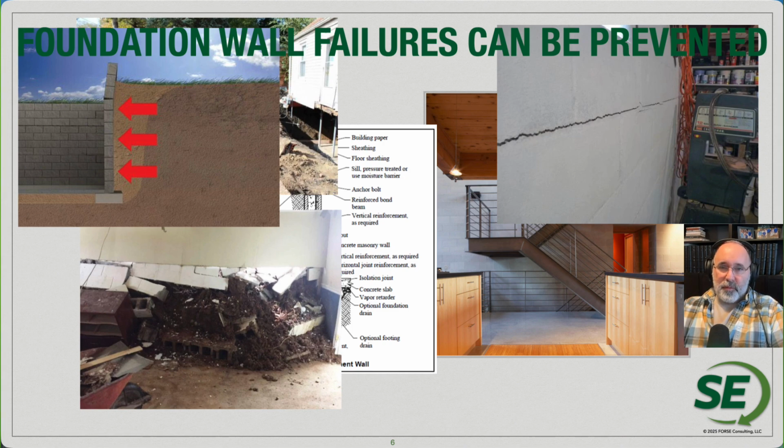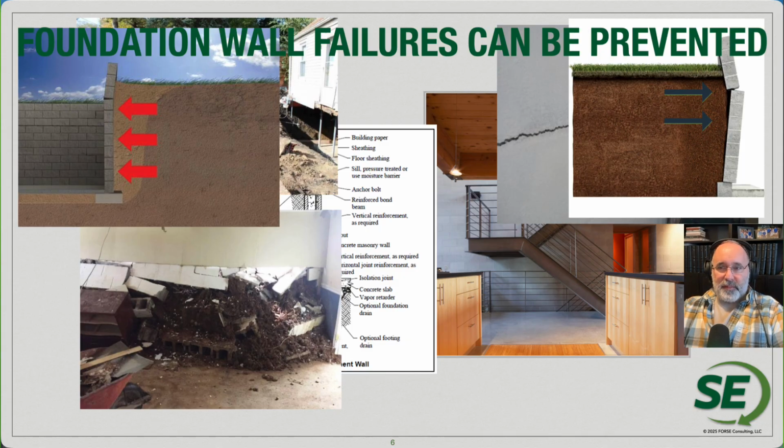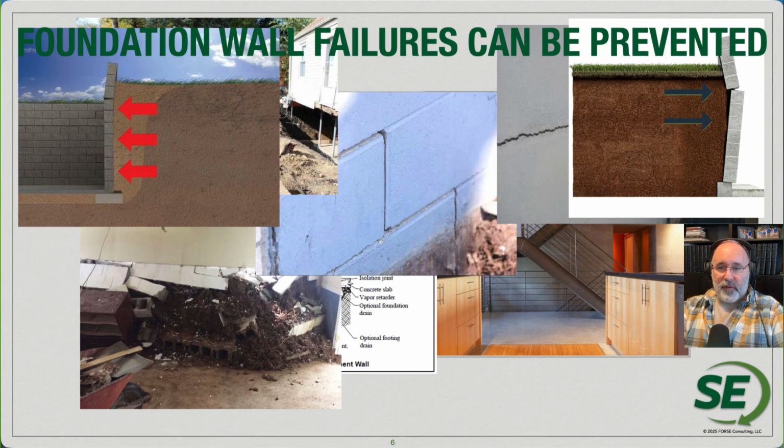In historical masonry foundation walls, there was a point in time where people didn't see the benefit to adding reinforcement to their foundation walls, whether they were concrete or masonry. And what you could see was that with masonry, that was very much a detrimental choice. Not having reinforcement in a concrete masonry foundation wall is what leads to those horizontal cracks. We have that excessive horizontal force. Maybe it's poor site conditions, poor soil. The soil is not draining the water. Maybe it's retaining the water. Frost is then causing that soil to expand quite a bit and causing some very large horizontal pressures.